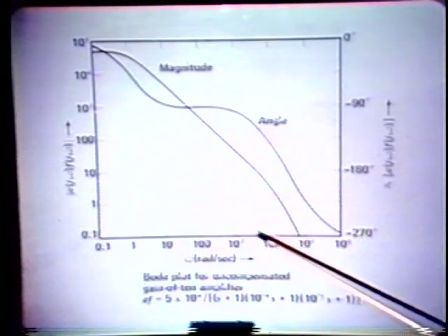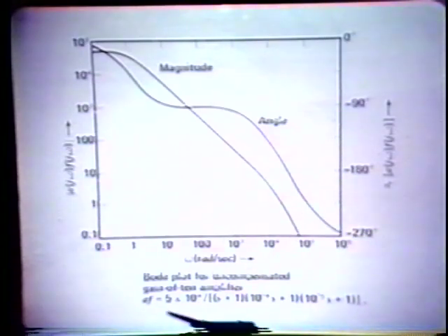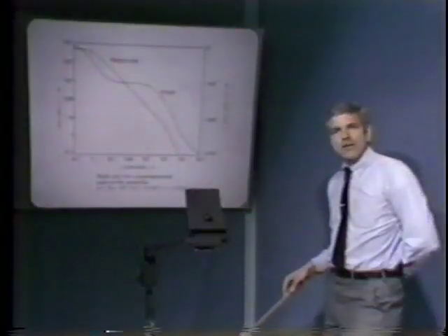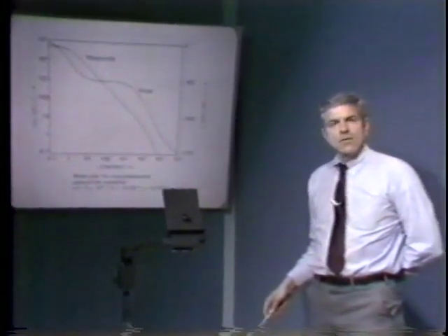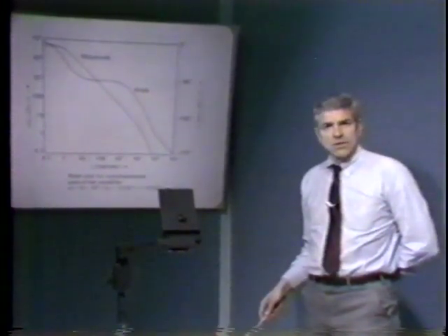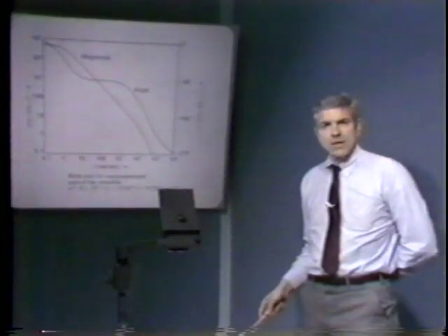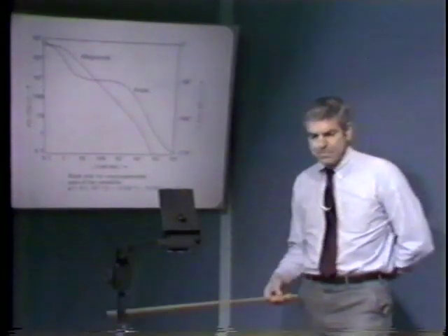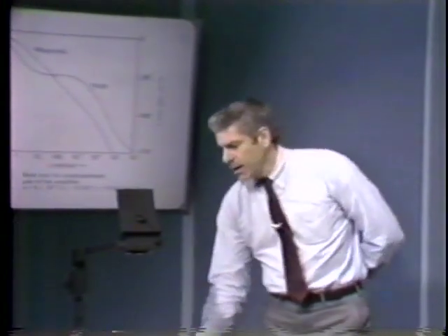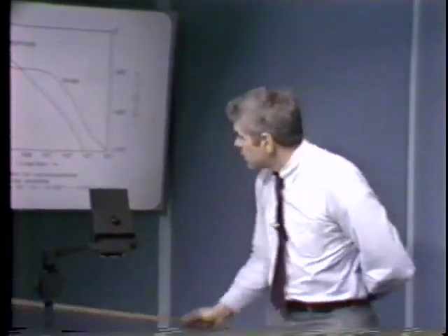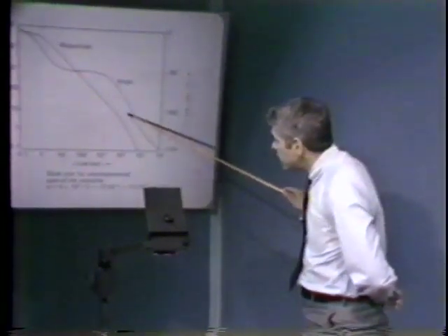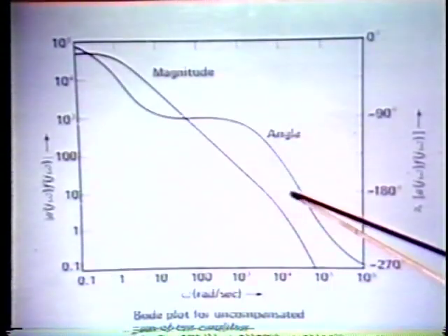And you rapidly begin to home in on a location for the 0 that will result in the maximum phase margin for the system. This isn't a mathematical optimum, but you can very quickly find out where you ought to locate the 0 to get the maximum phase margin in the resultant system, or awfully close to the maximum phase margin. And if we do that, we find out that a good location for the 0 is somewhere on the order of 2.5 times 10 to the 4th radians per second.